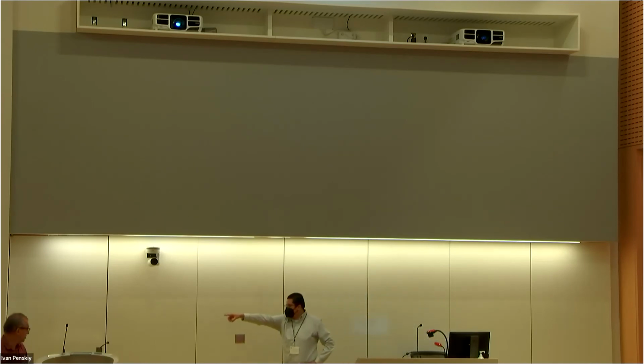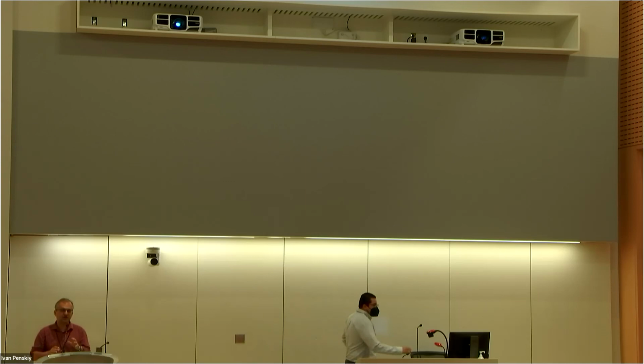Do you model the actuator dynamics in that, or do you need to add it? What basically we do is we calibrate it. So we come up with, for example in this case, a polynomial model that relates it to the input. We have done that calibration offhand, but it's not a dynamic model that we are working with right now. But that's a challenge: for more power density, I need something else, and I need to model the dynamics more.